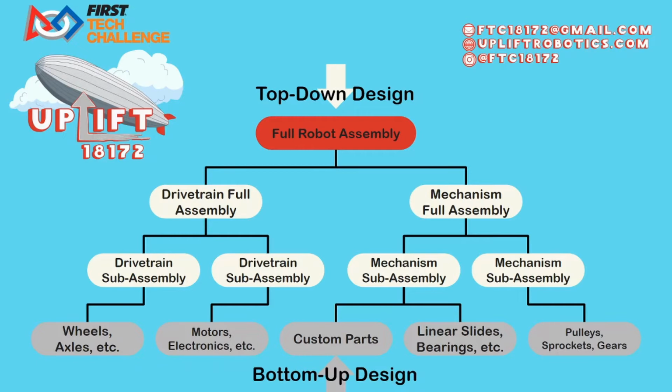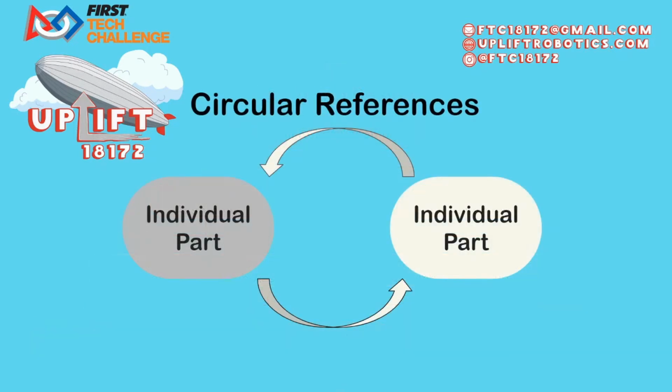Skeletons are also designed in ways that accommodate for changes that you can predict for your mechanism, making implementation of these changes much faster. They also create a central location for any changes that need to be made and prevent circular references. Circular references are two or more parts that take features from each other that the other relies upon, which makes the features create a circle where they can't be changed. There is also a third approach in middle-out design, which combines the top-down and bottom-up design processes into one.